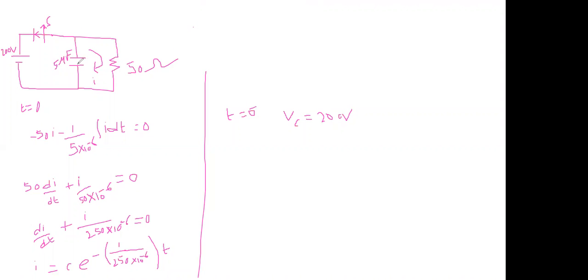Before the switch is opened, the capacitor voltage can't change abruptly. What is the meaning of that here? The capacitor is treated as an open circuit. When the capacitor is open, the applying voltage is 200 volts and the resistance is 50 ohm. Then what is the current here?